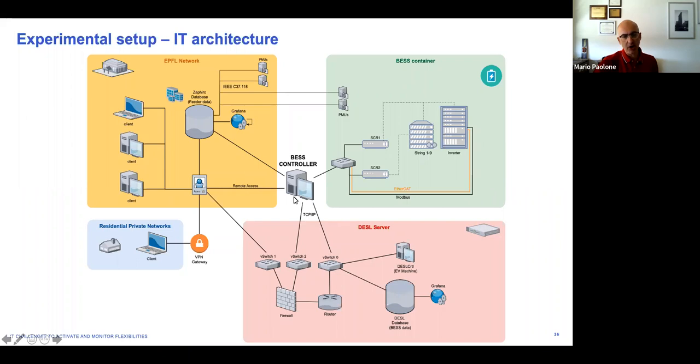This BSS controller is also connected to the database, which is accumulating data from the PMUs. The PMUs are streaming data through the IEEE protocol C37.118, and the retrieval of the data is also happening in real time. Just to give you an idea, the latency here is normally tens of milliseconds. Outside, we have a server, which is storing all the data collected by the PMUs and by the BSS. This is how the architecture has been designed.